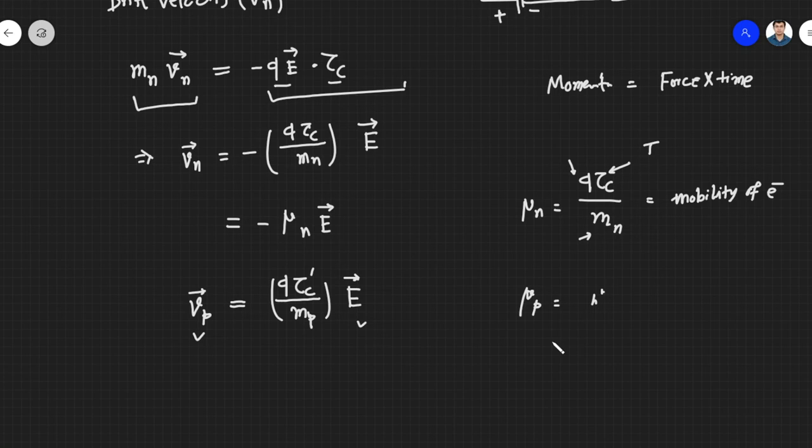And also at room temperature, the atoms are not idle, right? They are vibrating, and that is called the phonon. Each lattice point, each atom, is vibrating about its position. Because of these vibrations or the presence of the lattice, electrons and holes will get scattered.